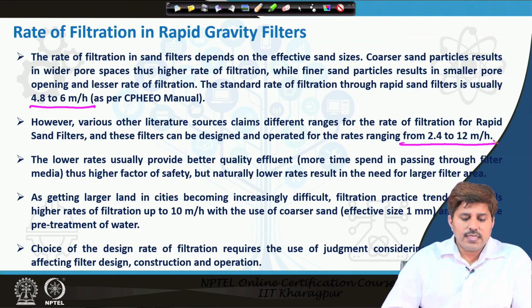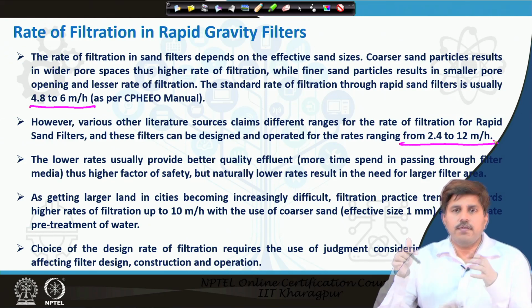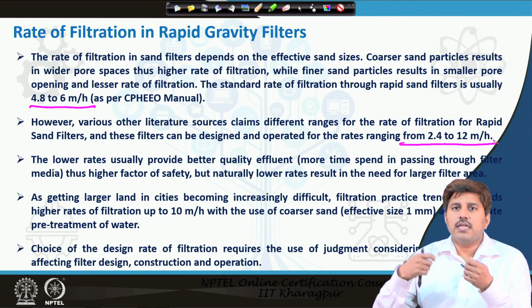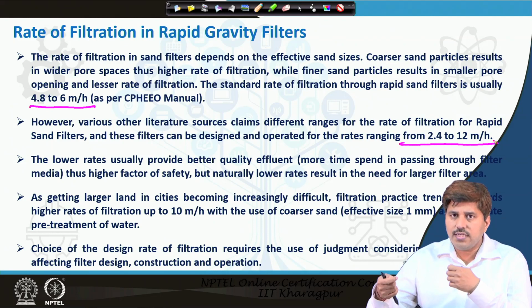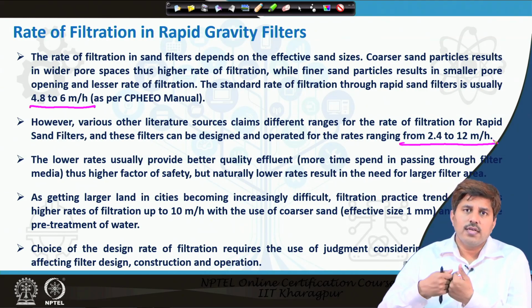Whereas if we go for a higher flow rate, that means water is passing much more quickly through the sand bed. So, the efficiency is going to be lesser.